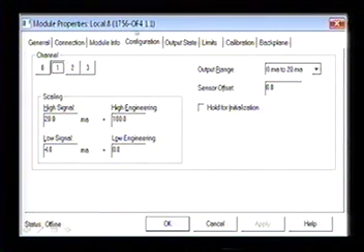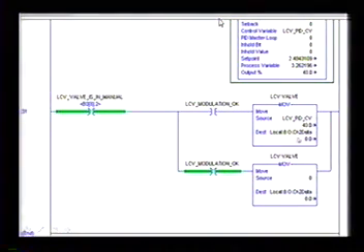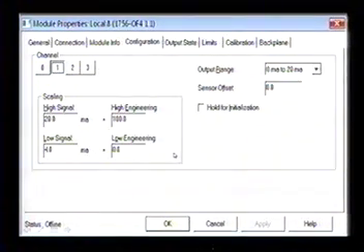And then on your output card, right here, remember it says 1 here, so let's check that out. It says channel 2 here, so I didn't display the right one, but you'll get the idea when we go through it. We should have hit 2 here and said 20 milliamps equals 100 and 4 milliamps equals 0. If the valve gets 20 milliamps, then the valve will fully open.